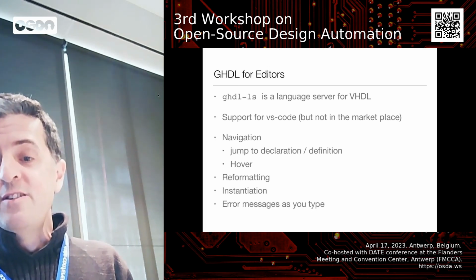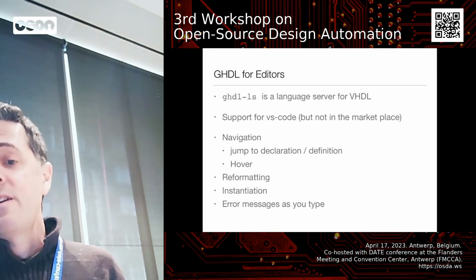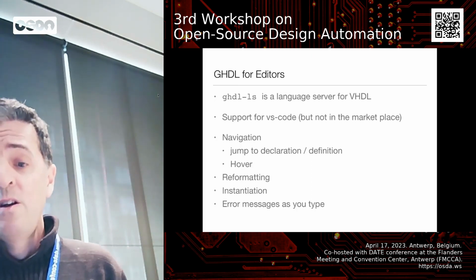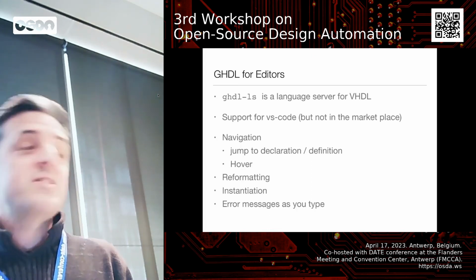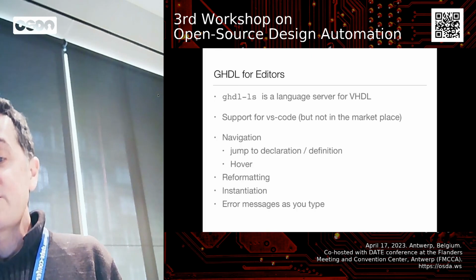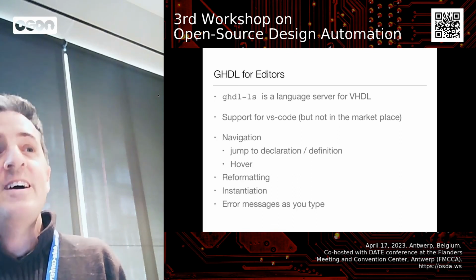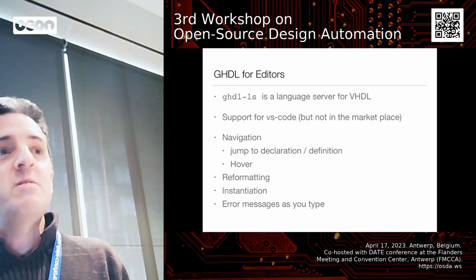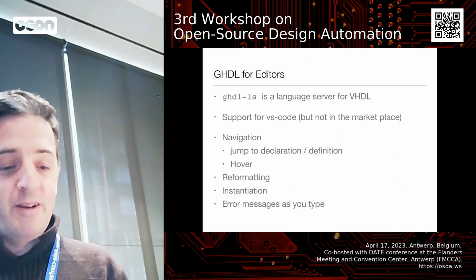There is the GHDL language server, which provides a language server for GHDL, and so it allows integration with Emacs or VS Code or whatever. It's quite good for navigation, and there is some support for reformatting and insertion. I am maybe not the only user, but one of the few users, and it quite improves productivity, because when you start the simulation, there will be no syntax error. Ideally, it always works immediately.